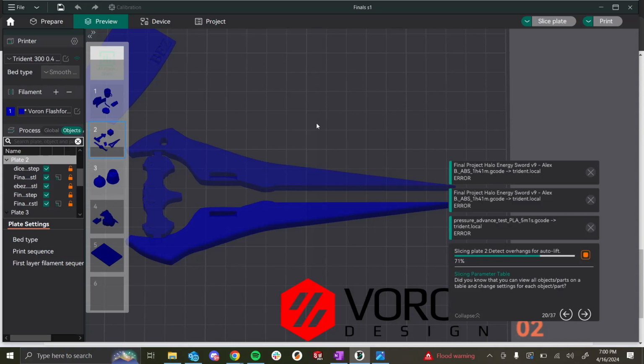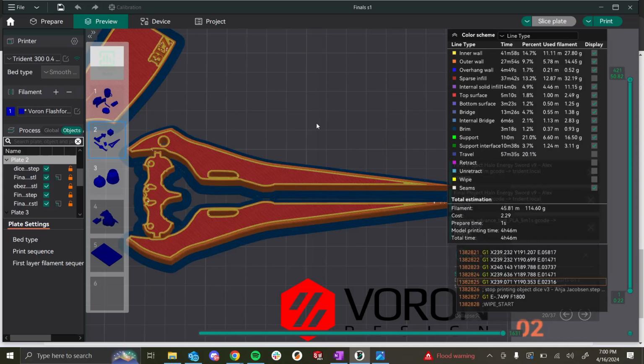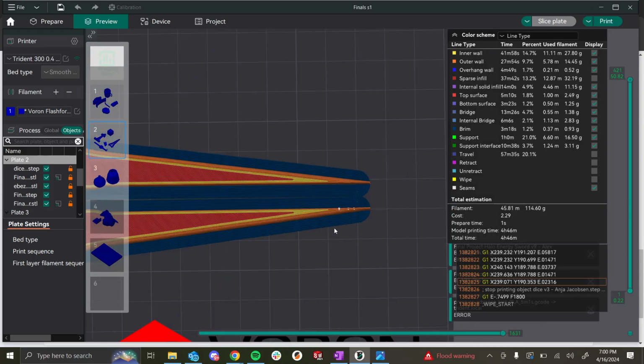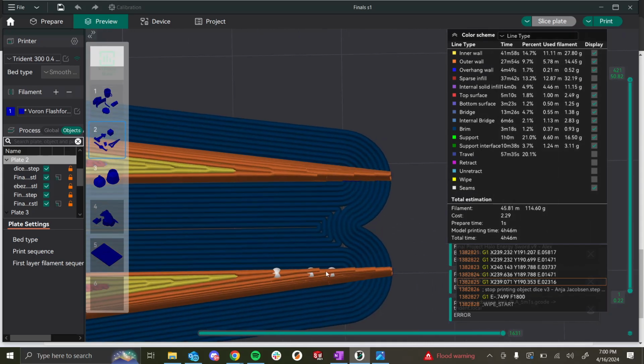But if you can design it so that it doesn't need that, it'll be better because that means less post-processing time, which means either I or whoever else is printing it doesn't have to take supports or the brim off. You can just take the part off and use it. But obviously, for something like this model where the geometry is very specific, it has to be pointy, so you resort to using this brim. So this blue area around.